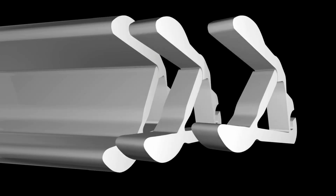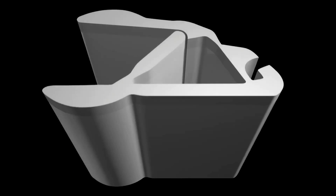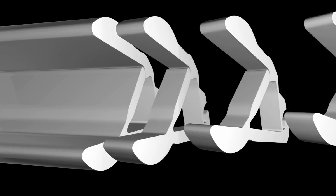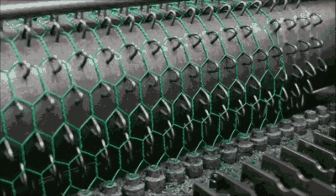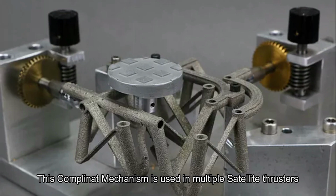Because they get their motion from flexible regions, many compliant mechanisms can be fabricated flat from planar sheets of material. The price. Because they have fewer parts and simple manufacturing processes, compliant mechanisms can be very inexpensive to manufacture. Performance. Compliant mechanisms have a smaller number of movable joints such as pin and sliding joints. This results in reduced friction and need for lubrication.